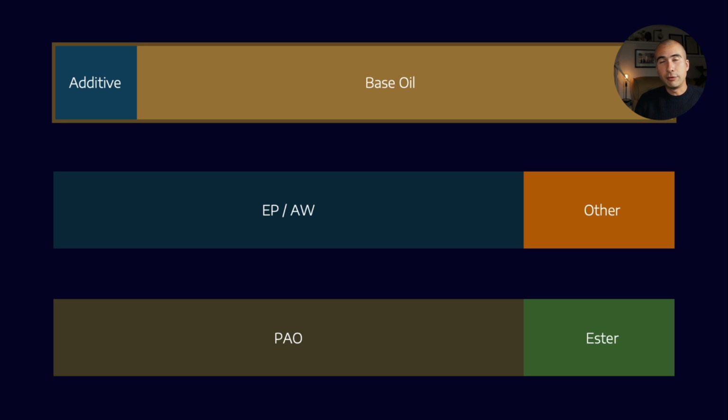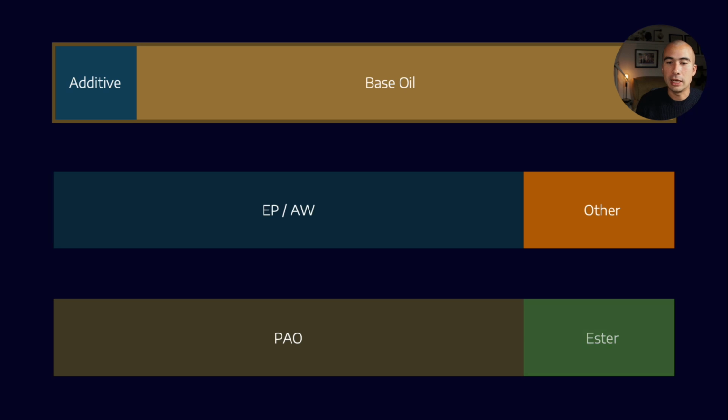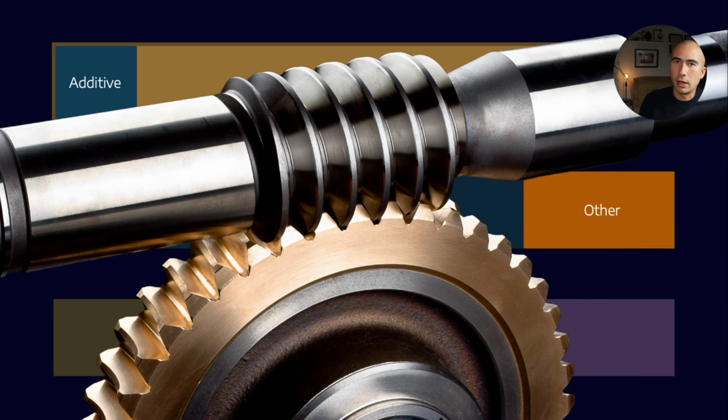Now, there are variations on synthetic gear oils as well. So for example, if we are looking at really high temperature applications, I've seen examples where the ester gets swapped out for an alkylated naphthalene. Or in some instances the alkylated naphthalene is actually the primary base stock and the PAO becomes the co-base. I've seen that too.